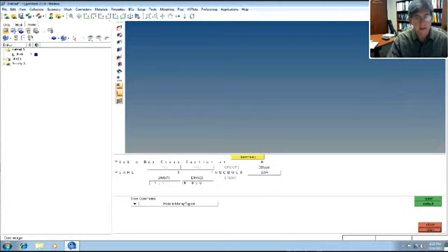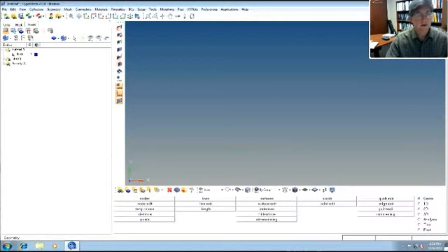0.125. Okay, that's that dimension. And this dimension is the 3/8, which is 0.375. Okay? So there you go. It's now defined. I don't know why it does this group thing. It sets that for you as part of it. HyperMesh keeps track of that by itself. Okay? Return. Okay, so now that's created.